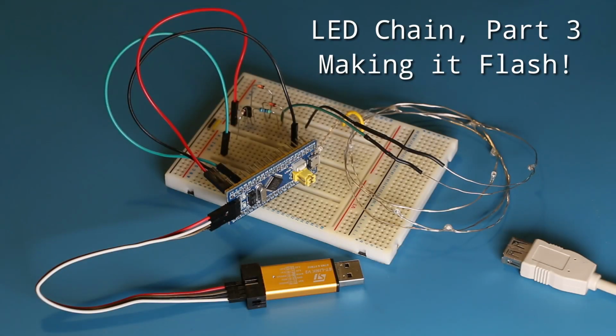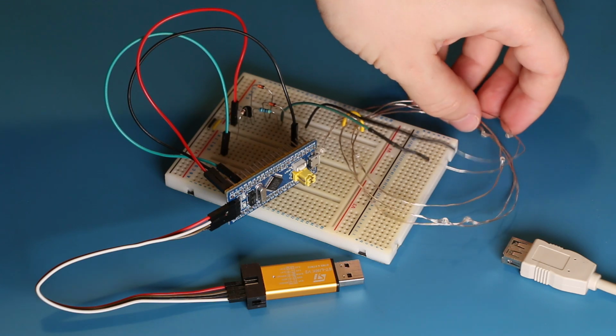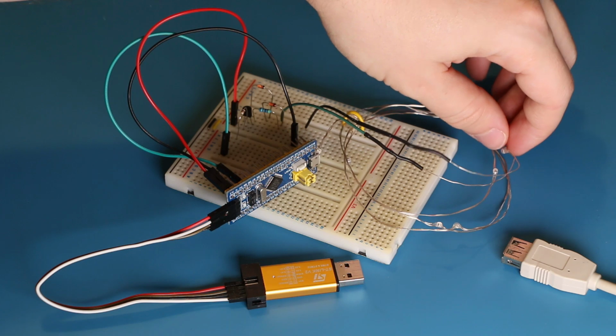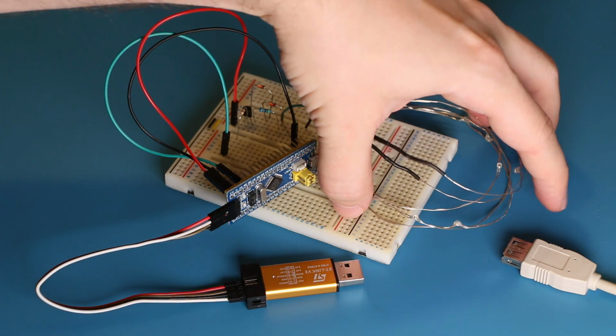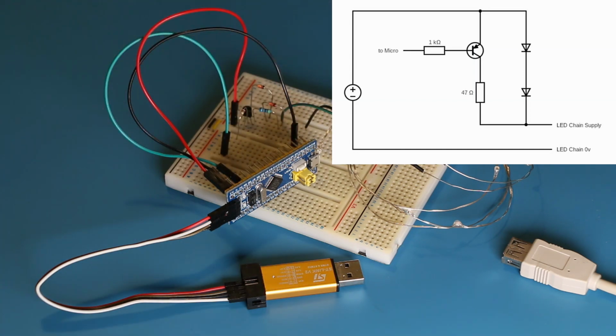Hi, in this video we're going to continue looking into this 2-wire RGB LED chain. In the first video we looked at the protocol that's being used to control the chain and identified that there are two sets. There's the odd set and the even set of LEDs. In the second video we had a bit more of an in-depth look into what's going on the wires, and we also built up this very simple control circuitry and connected it to an STM32.